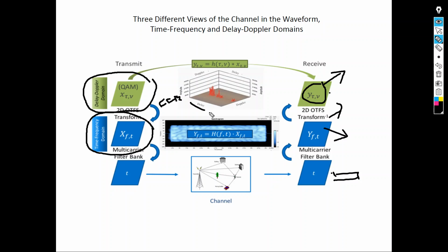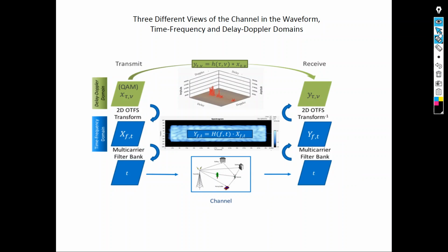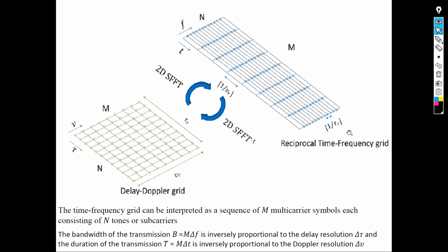And this is the channel. This is the convolution process, multiplication, and this is the physical parameters of the channel that you are transmitting over. And this is using variables and numbers. For example, I told you you build a matrix, yes? And this is along tau, this along nu. Tau here, after the 2D symplectic Fourier transform, fast Fourier transform, think of it as FFT2.